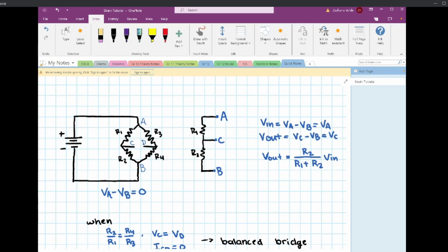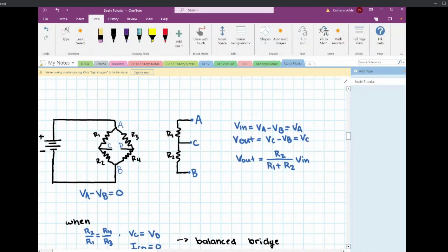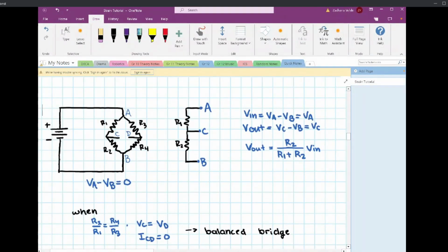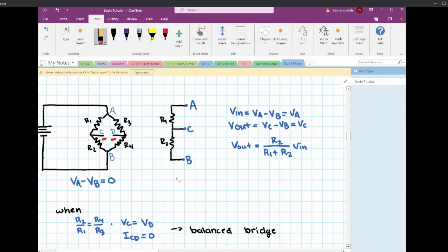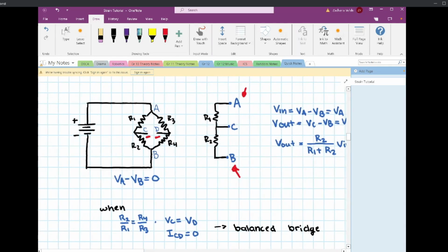Well, as a refresher for most people, and new for some people, this is a Wheatstone bridge. You have 4 resistors in this arrangement. You have power being provided on this side, and you have 4 nodes. And through the concept of voltage dividers, you're able to get the voltage out through each of these legs at point C and at point D. So you know your VA. You know VB is whatever your V minus is. So for most cases, it's 0 volts.